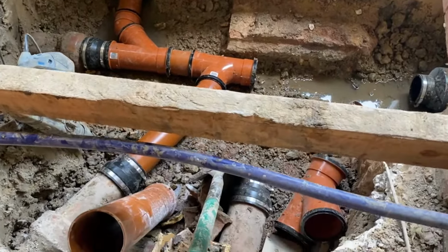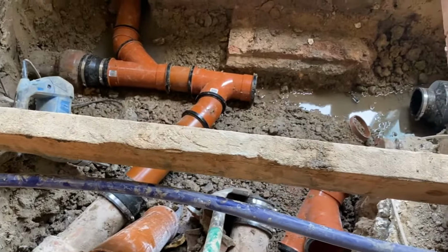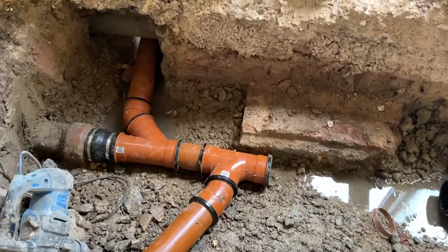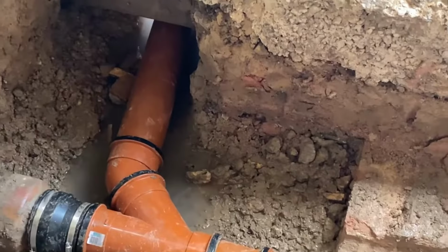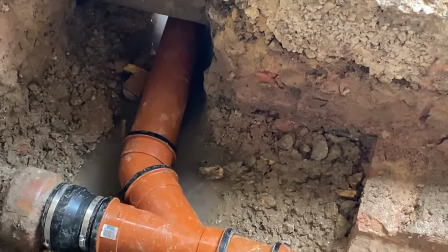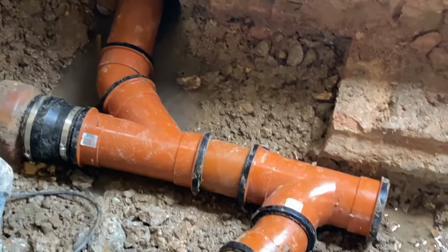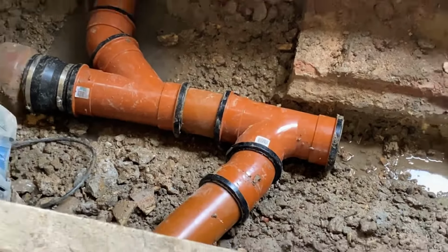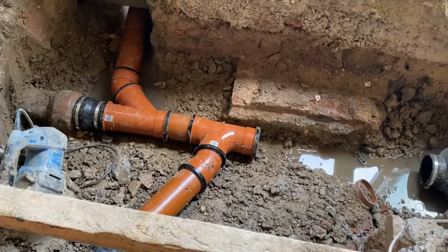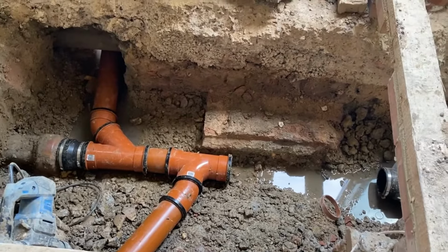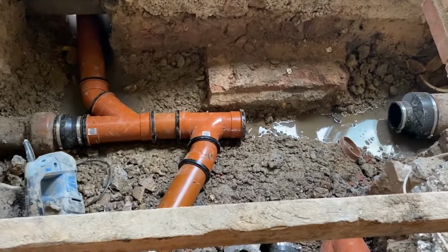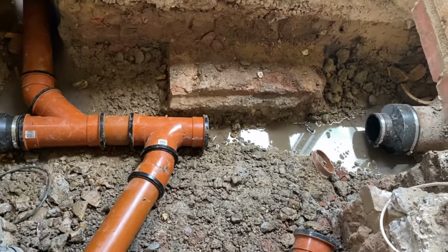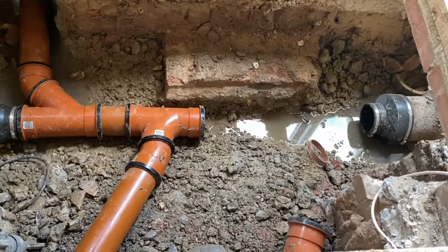So we just need to now connect this last pipe on the right hand side on the bottom here, and then join up the other end of the sewer on the right hand side, and that will be the full connection done. But this is the pipe that's going out to provide the rodding access, and then the main sewer is waiting to be reconnected to the other side, which we've also put a connector onto the old clay pipe on the far side, so it's all ready to be reconnected up and it will be live again.